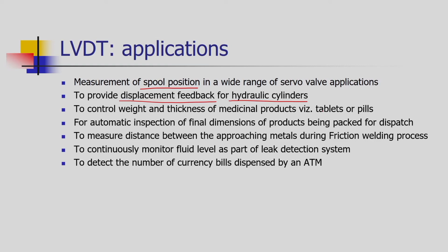LVDT sensors have a very important application in the pharmaceutical industry, to control the thickness of tablets and pills when manufacturing medicinal products. To have the precise thickness, LVDT sensors are used. If the tablets or the pills do not have the precise thickness, they may be discarded. Then, to automatically inspect the final dimensions of the products, these sensors are used.